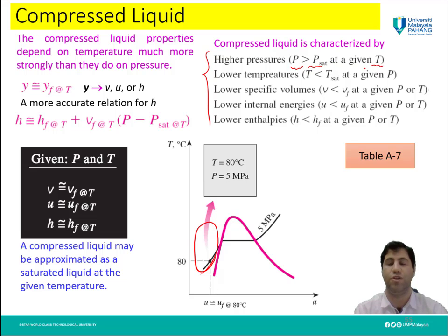You need to compare the pressure you have for the water with the saturation pressure of water at the temperature you have. If the pressure is higher than the saturation pressure for that temperature, it means it is in the compressed liquid region.